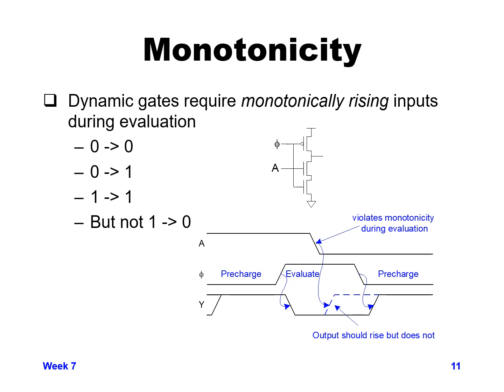But we can't ever have the input start as a 1 and switch to 0 during evaluate. So we have an additional timing check that says we can never have an input switch from 1 to 0 during evaluate, otherwise we're not going to get the right value out. This is an additional timing check that normally we don't have on static logic stages, but we will have it on domino stages.